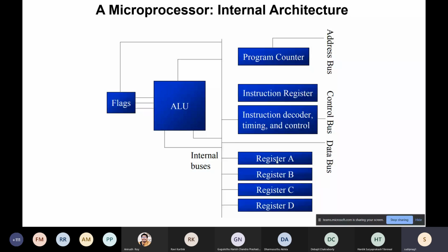You have stored the result, but your addition may generate a carry, as you have added two 8-bit numbers. Register D was 8-bit, and register A was also an 8-bit value, right? So after the addition of two 8-bit values, you may generate a carry. Where will it go?